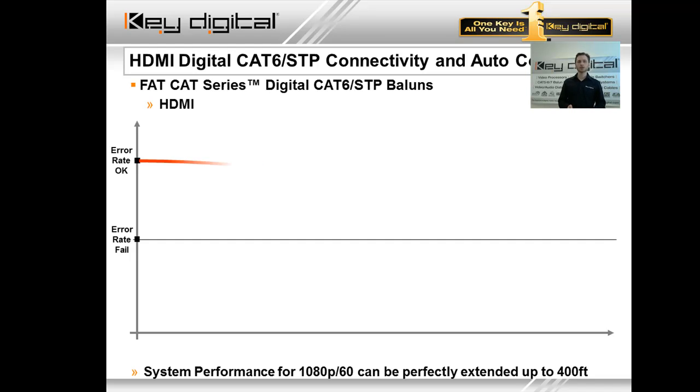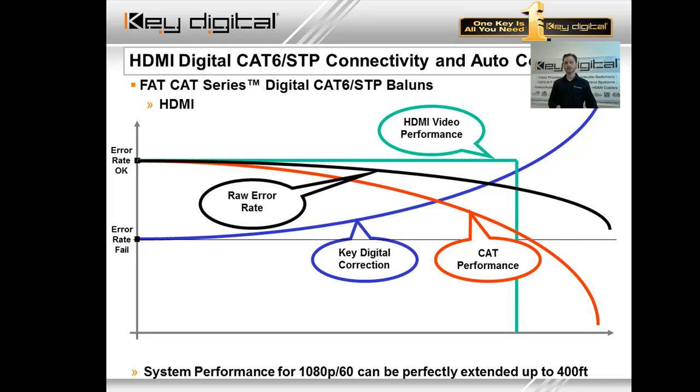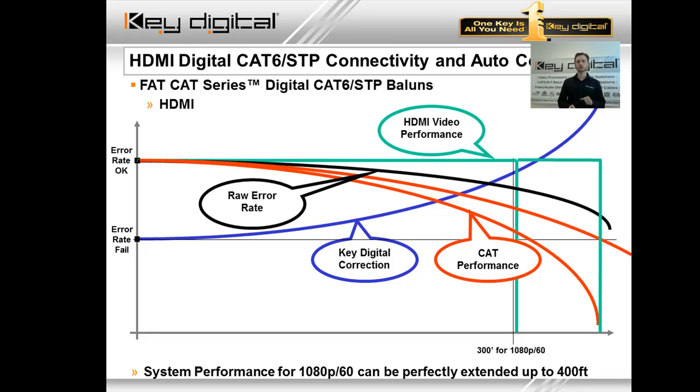So a graphic here showing you the performance offered by the HD 8x8 BT. It marries in with that Key Digital Cat6 STP1X to deliver 400 feet at 1080p, or third-party cabling, 300 feet 1080p. Again, 500, 600 third-party Key Digital for your 720p or comparable resolutions. And this is HD 8x8 BT with KD Cat HD 500 RX, as in receive.